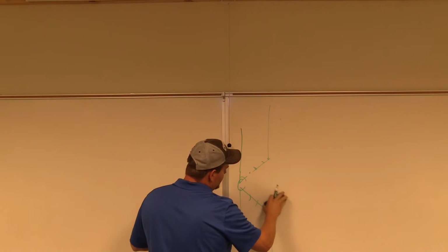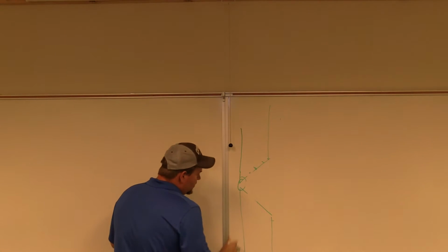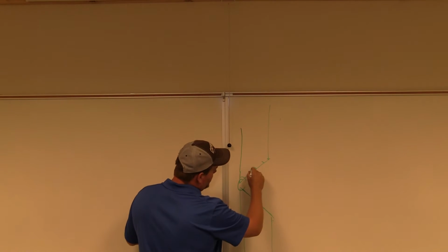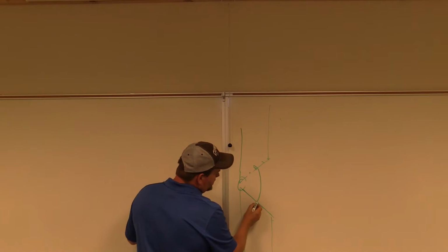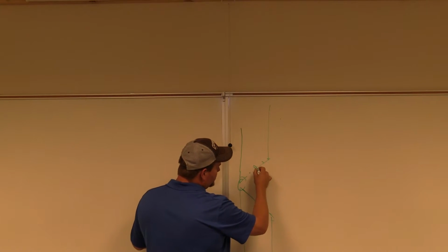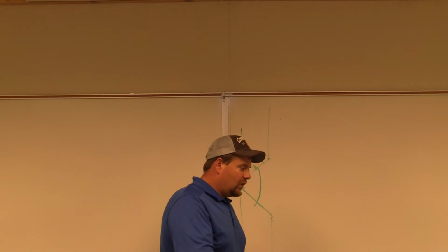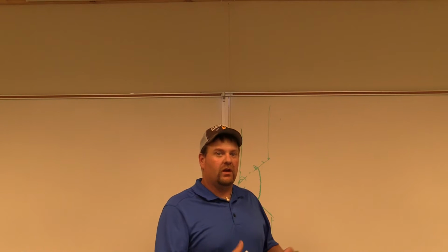That silica specifically comes out here, say it's here, and it sits and solidifies right here on the surface of the weld, at the weld pool, right? Because that's what it is. Anytime we melt something, the impurities always come to the top of the weld puddle. That's the whole reason for welding, so that it comes to the top and to the surface. If we need to, then from that point, we grind it off, clean it, and so forth.